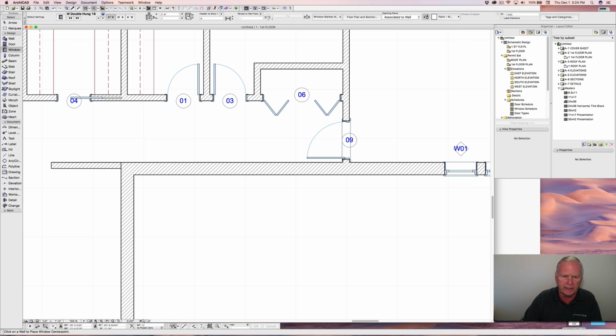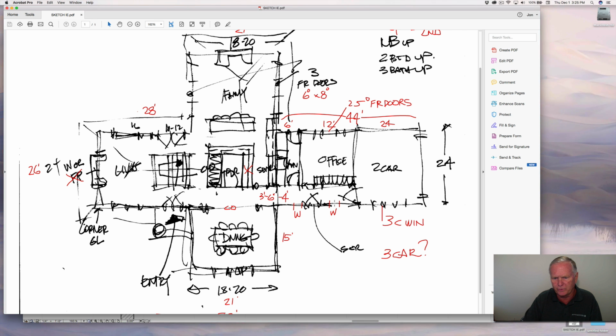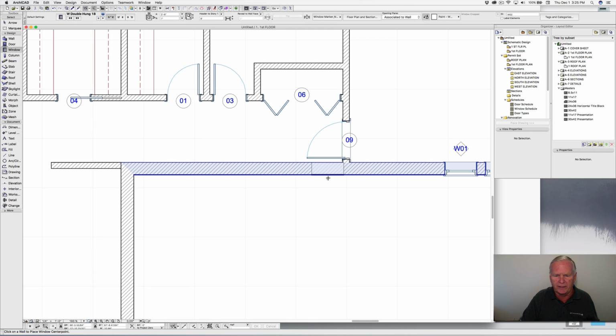I did forget an exterior door. Let's go back over here. We've got that exterior door, and we have a couple windows flanking it on either side. So on the fly, we're going to go back and get the door tool and a door setting, and we're going to do that by highlighting that and holding down the Alt key and just go over a hotspot. You can get them in a lot of different locations, and you'll see the name actually come up of what you've got selected, and just suck up those settings.